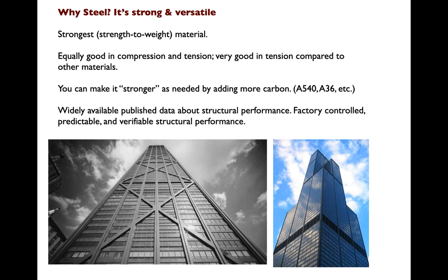The primary way we do this is adjusting the carbon content. More carbon makes for steel that is generally stronger, but also more difficult to work. And the sort of fine balance that we have typically is what we call architectural steel, or A36 steel.